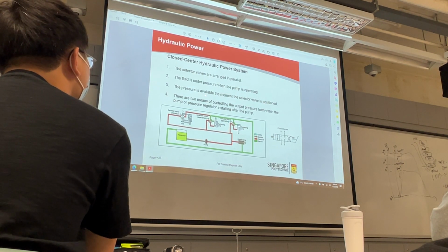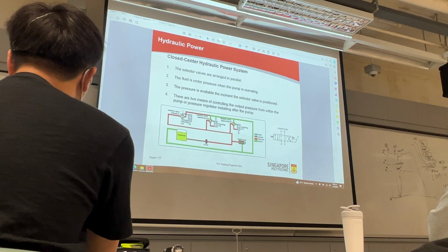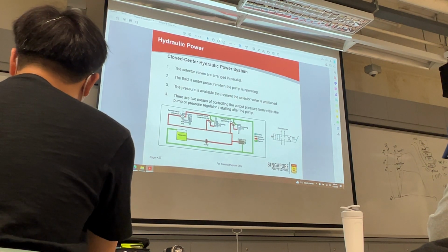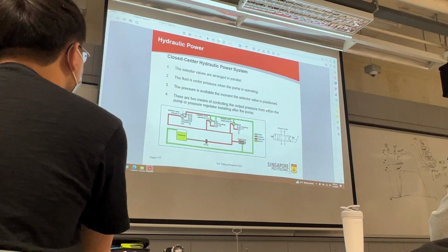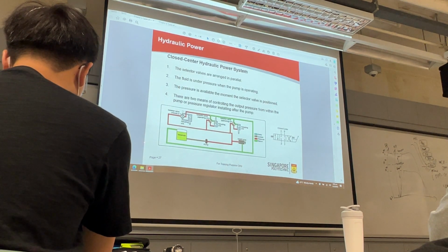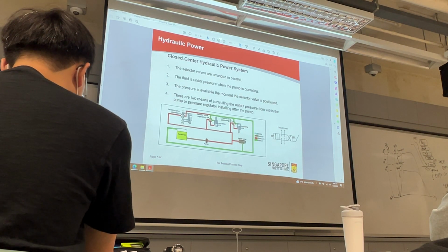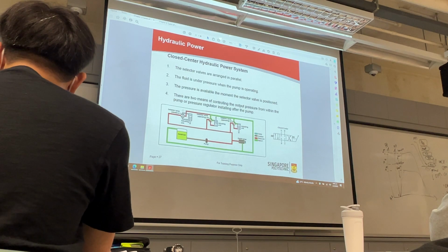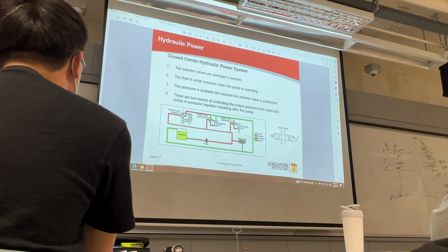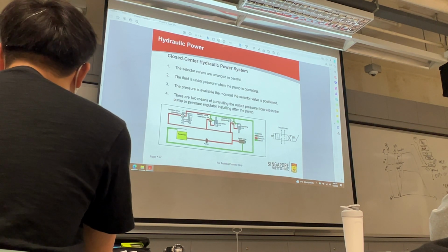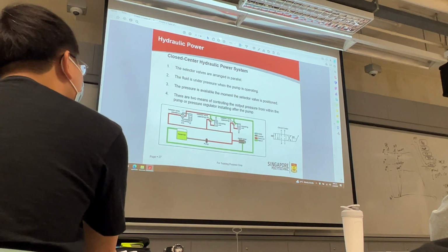Now, fluid under pressure and pump operating, yes. When you switch on the variable displacement pump, what happens with the pressure? Instant pressure. Your pressure is available at the moment of need. Correct? The moment you have 3000 here and you select your actuator, it will respond immediately. This one has a delay, this one has no delay. This is what we want. Okay, we shoot when we get the time. This one has a delay: you press the button for the bullet, maybe the bullet takes 1 second later, but in the meantime the airplane has flown away.